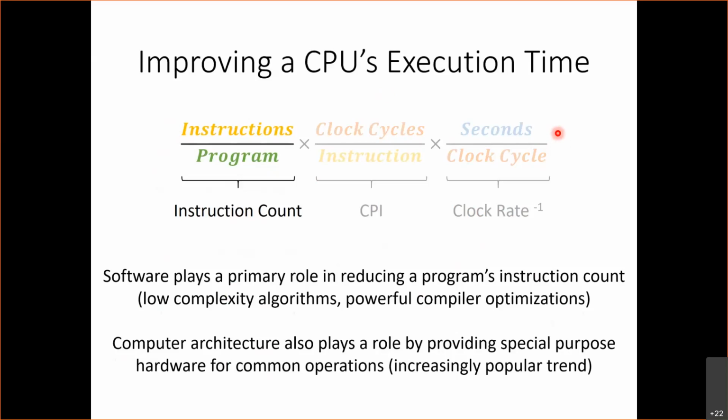A cycle in a CPU will always take the same amount of time, because there's an oscillator oscillating in the CPU to drive this clock, and this oscillator is regular. Every pulse will take the same amount of time. The average here comes in the CPI. So when I say cycles per instruction here, yes, it's a correct observation that I mean the average number of cycles per instruction, because some instructions might take more cycles than other instructions.